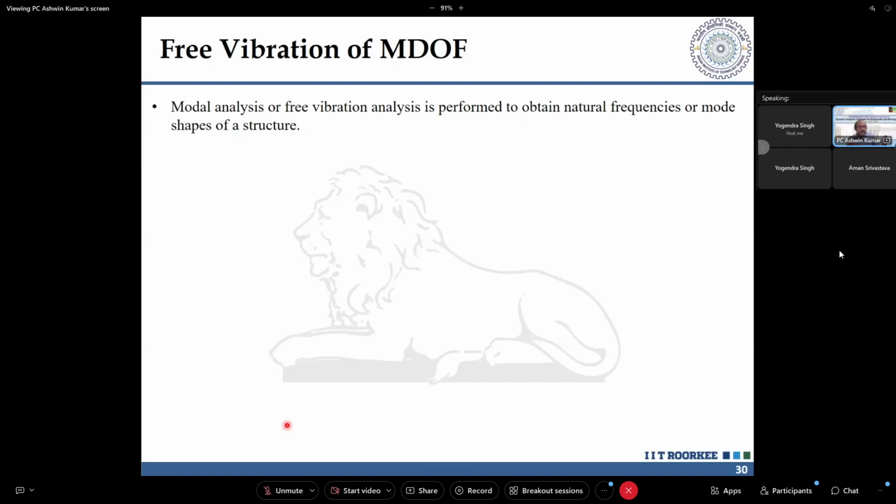To assess how many frequencies are going to occur, think back on the degrees of freedom that we talked about. Again, the same thing comes in. Was it a 3D structure? It might be, but the motion was in a 2D fashion. So I'm doing a 2D analysis of the structure, subjecting it to left to right motion. So you might say there is an X, there is a displacement U1, U2, and there might be a rotation also coming. The mass was not providing any rotation, leave it out.